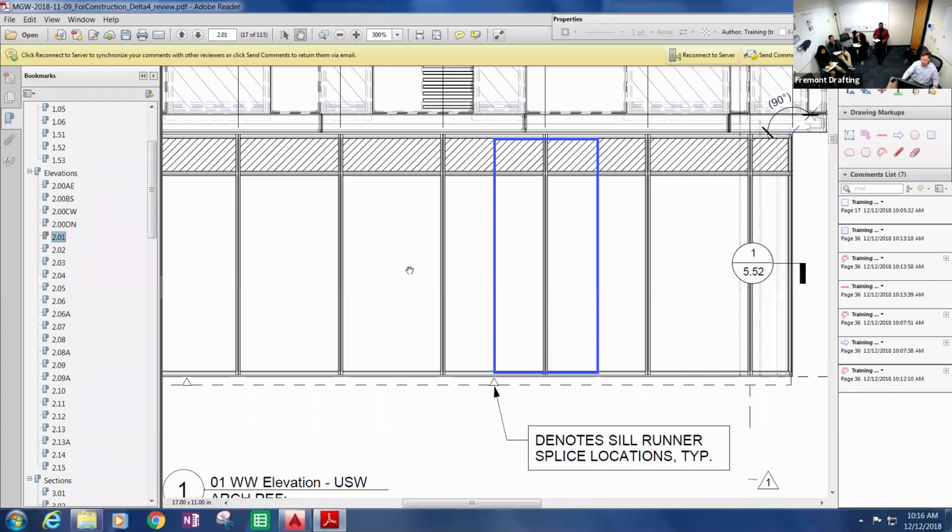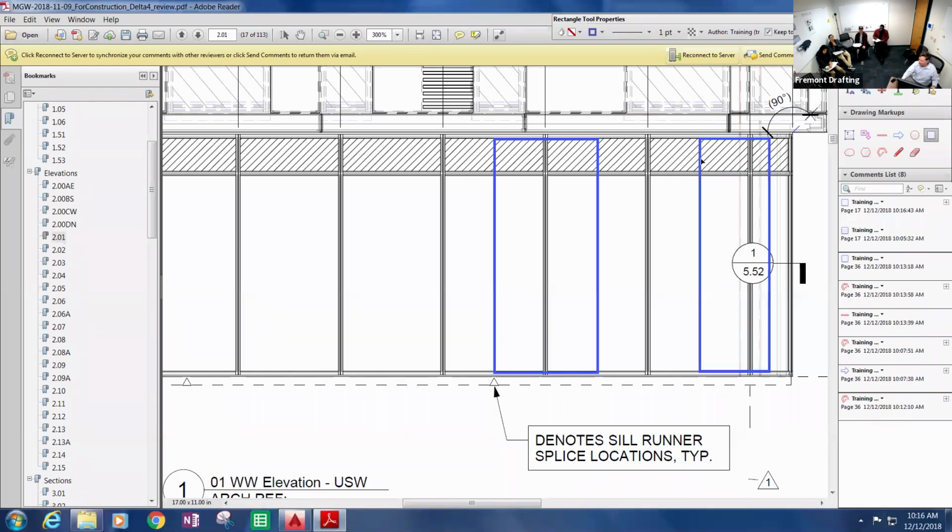So in the tributary area, when I'm looking at the vertical mullion, this is the tributary area that's going into that mullion. It's half of the bay on either side. Like in this one over here, the wind load on this vertical mullion is from there to there, because it's half of that light of glass, even though it's small, to over here.